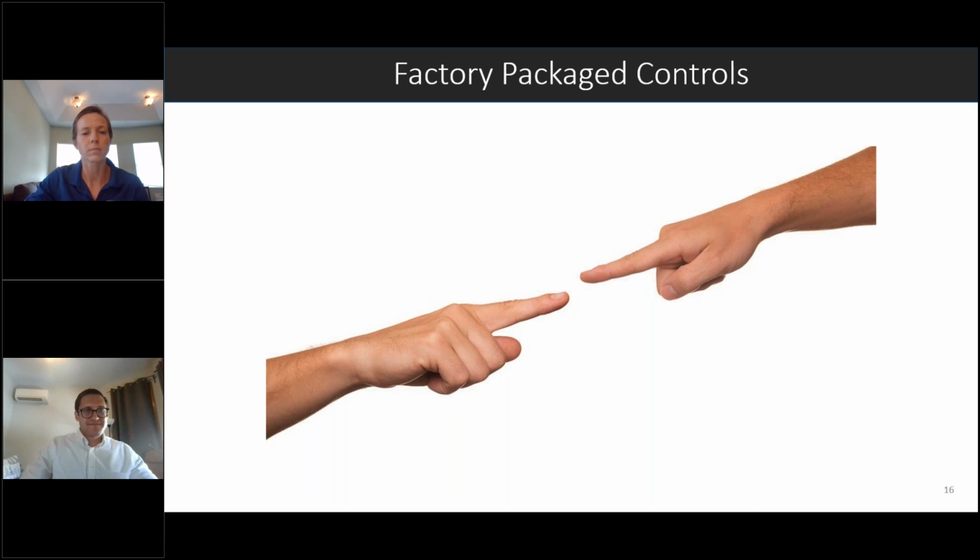All right, here's another question. Is the wireless option for Distech, this is a confusing question. The question's on our Distech controllers over IP. Is there a wireless option? And the answer is yes. There are actually 2 USB ports on every single one of our Distech IP controllers. Our IP controller line we call the Eclipse series. There's 2 USB ports on each. One of those can be used for a wireless transmitter. So then the controllers can talk to each other BACnet over Wi-Fi.